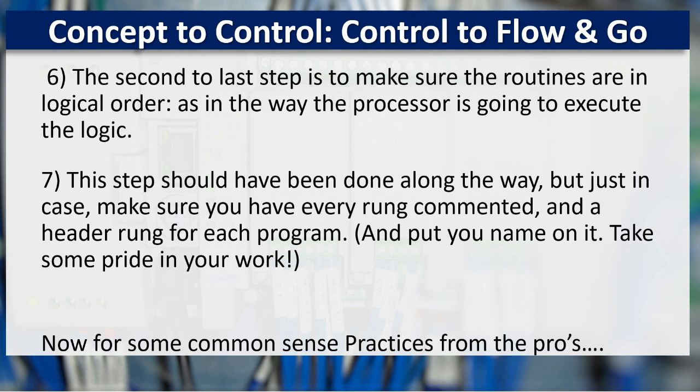The last step should have been done along the way, but just in case there might have been some changes or something or other, make sure you have every rung commented and a header rung for each program. And put your name on it. Take some pride in your work. Now, we're going to take a look at some common sense practices from the pros.